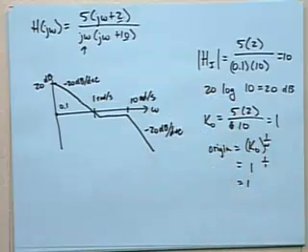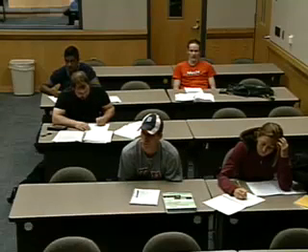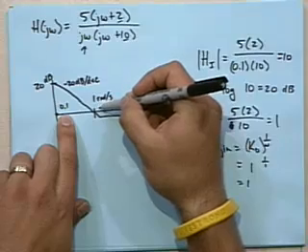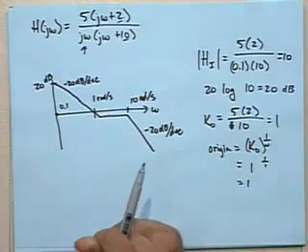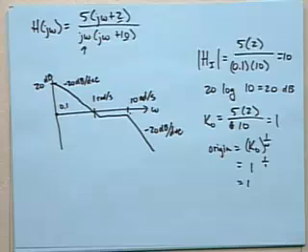Yeah? Okay, so the first line there, does that just start out decreasing at 20 dB per decade, or does it do that the whole time? Because I don't understand how that would work. Because if it was a negative 20 slope, it would cross at 10 radians per second. Well, I guess here's the thing. The difference between 0.1 and 1, that's 1 decade. That's the thing to remember. And then the difference between 1 and 10 is also a decade. And that's the weirdness of the log plot.